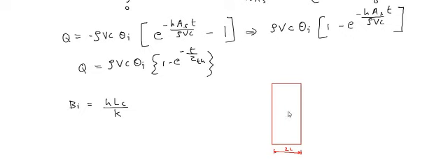The characteristic length is where you have a definite change. Here you get the temperature profile, with heat transfer from here to here and from here to here, because this is the heated material, so there is heat transfer to both sides, and this length is equal to L, which means that the characteristic length is L.